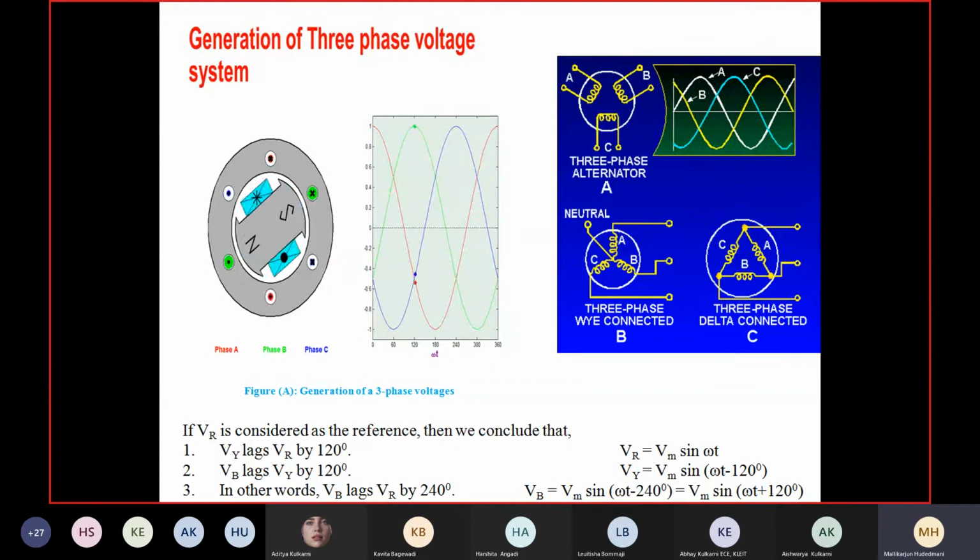So opposite to that, a group of conductors, a large number of conductors in the form of winding, are put in the stator. A number of poles of suitable pole strength are driven by the prime mover. The flux linked with the conductor changes when the rotor is revolving. Then induction of EMF in the conductor happens and it is taken out. It's a dynamic kind of induction.